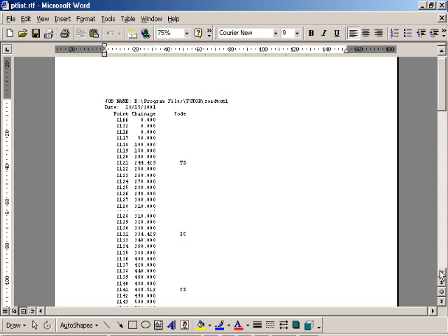If you've used other means of calculating your alignment, you may not have points coded with TS or ST. What you need to do, regardless of how the alignment was determined, is to prepare the chainages of the points that are at the start of the curve where you wish the superelevation to commence applying, and the end of the curve where the superelevation should finish and taper back to the standard crossfall. Once you have these values for each of the curves, you're ready to proceed and fill in the super table.